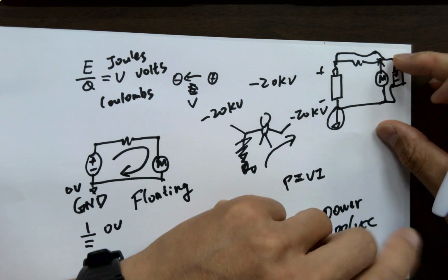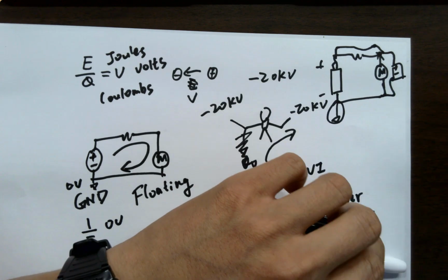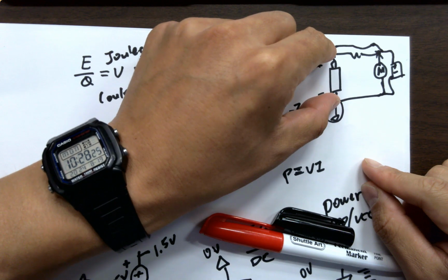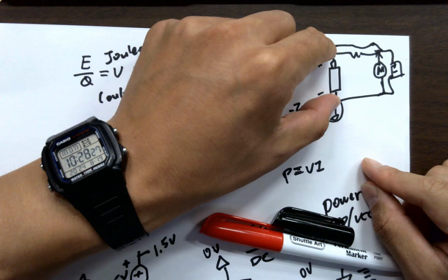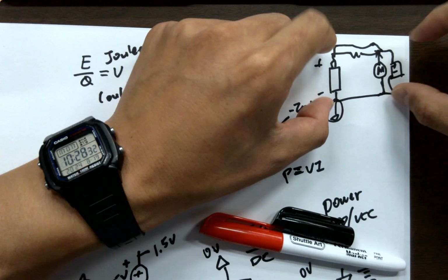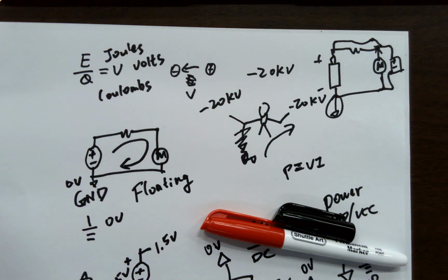So all the circuits have the same baseline. You have 1.5 volts from here to here, and that 1.5 volts will be treated as 1.5 volts for the chip as well, because they share the same cathode. So they share the same baseline, and they know they are each taking 1.5 volts at the same time. That's the meaning of ground. It's the baseline, or 0 volts, of the whole circuit.